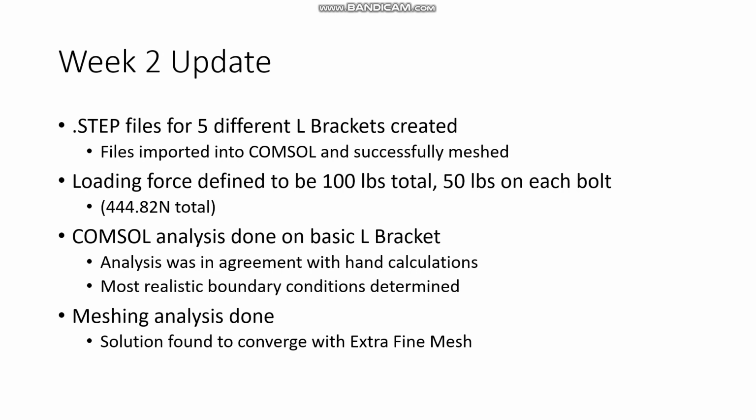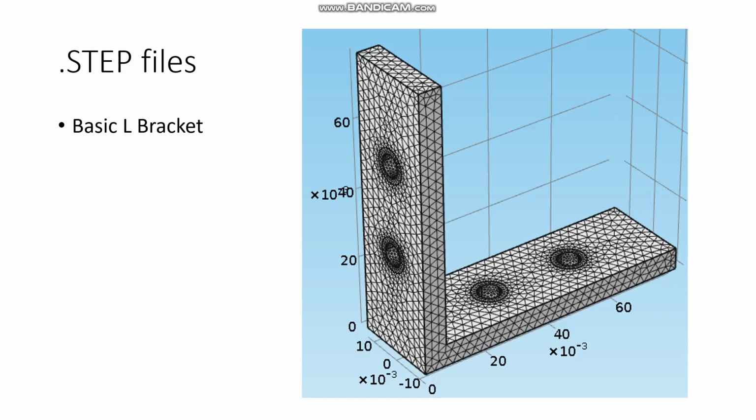This week I created a CAD model of 5 different L brackets and verified that they would properly mesh in the COMSOL software. I locked down a loading force of 100 pounds spread evenly between 2 bolts. Also, I verified the COMSOL model for the L bracket against the calculated stress and found the most accurate boundary conditions and loading conditions. Finally, I found what size mesh the solution converges.